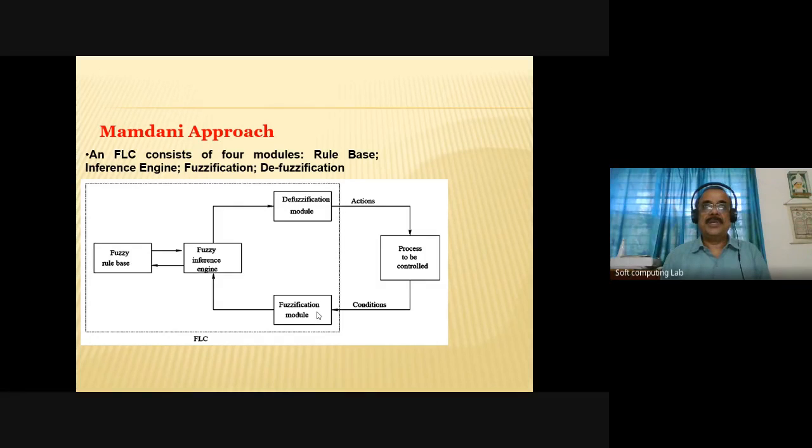Okay. Now, supposing that, let me take a very simple example. Supposing that I have got 2 inputs and 1 output system, say, for simplicity. Input I1 has got say 4 linguistic terms, like very low, low, high, and very high. And the second input has got another 4 linguistic terms, say humidity. Okay, once again, very low, low, high, and very high. So 4 multiplied by 4, there will be 16 possible combinations of the inputs. And for each of the possible combinations, there will be some output.